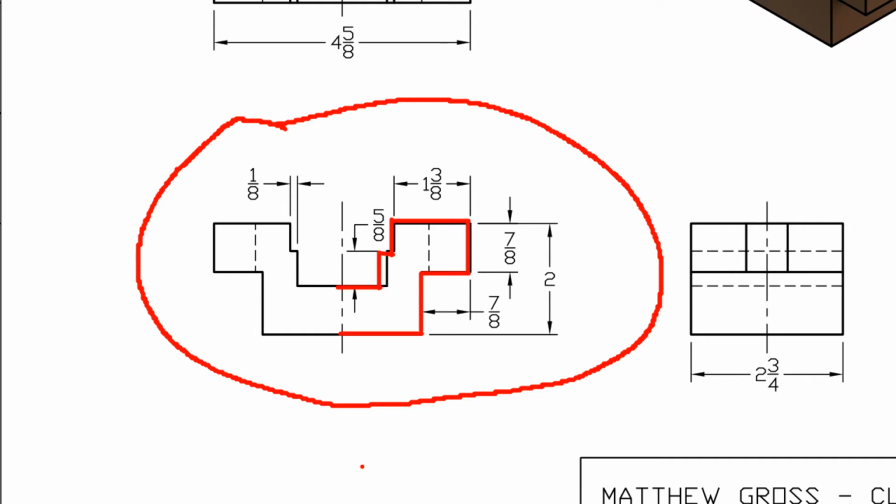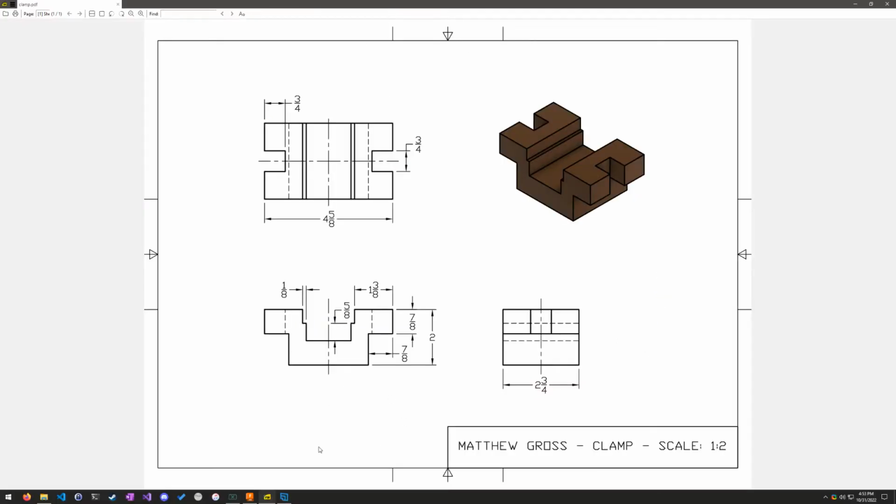just like that. I'm going to start on origin because then I'm going to mirror this, if you remember from AutoCAD, the mirror tool, so that this just goes ahead and does the same thing on this side, which of course means I can be lazy and only model half of this, which is good. All right, so let me go ahead and do that now.